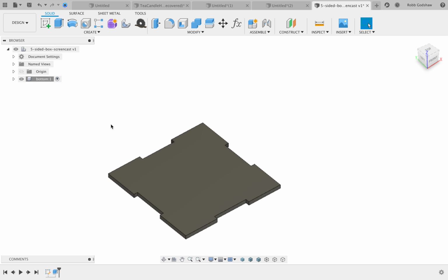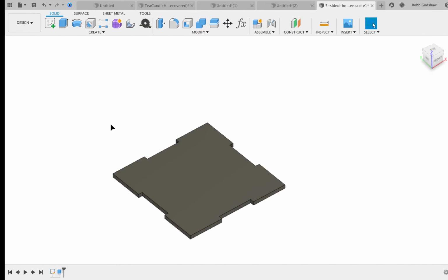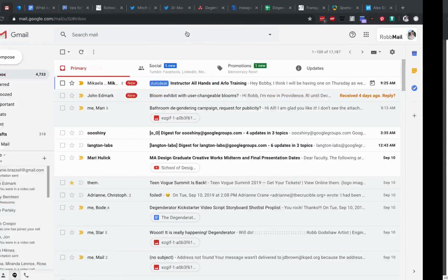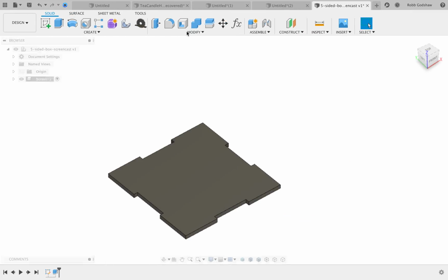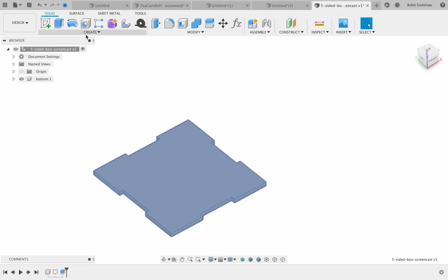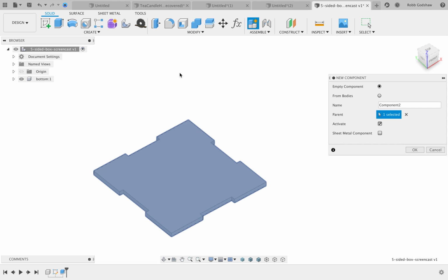But the sides are separate parts. And if you watch the tutorial in my Fusion YouTube video folder, you'll learn about the difference between parts and components. And essentially, a component is anything that is a separate thing, that moves independently and that exists as a separate part. And it's always best to make sure that everything is in a component. For example, I'm going to call this front/back.